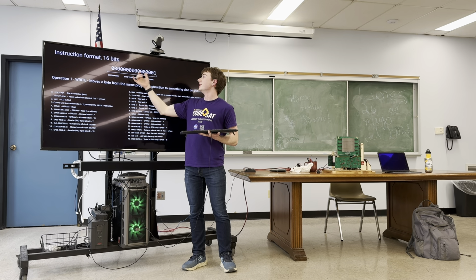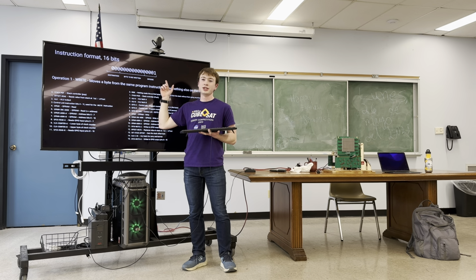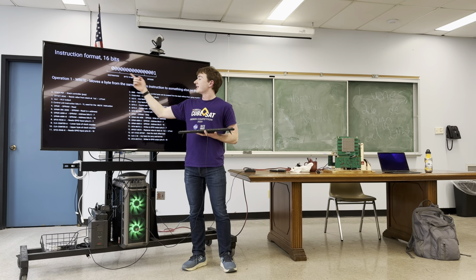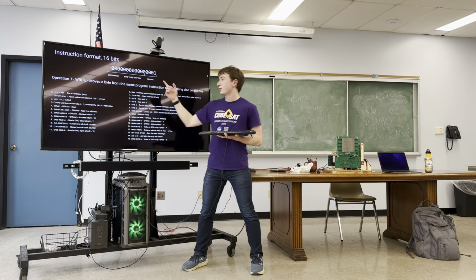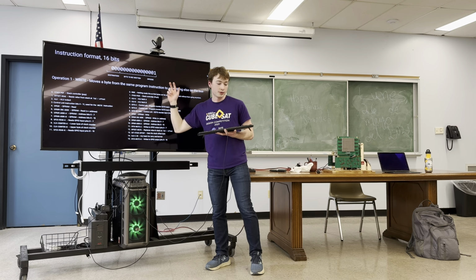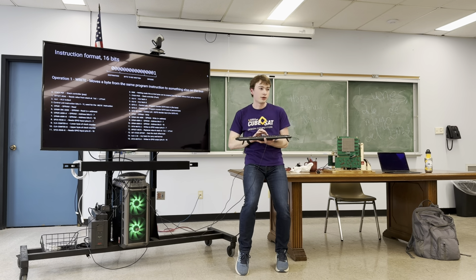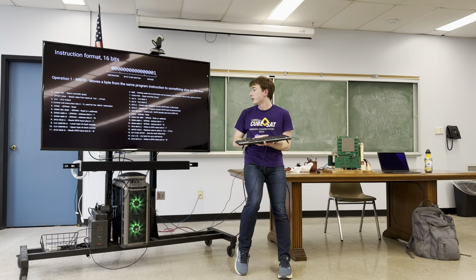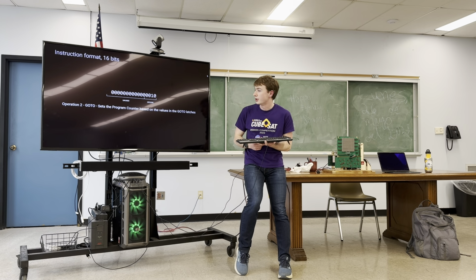But so this is 16 bits long. 4 of them are always reserved for the operation code, or opcode, that tells it what to do. And then the destination. If I had the source and destination, then I wouldn't be able to fit a whole constant byte from the program. So that's why write is a different instruction than move. And then these are some other ones.